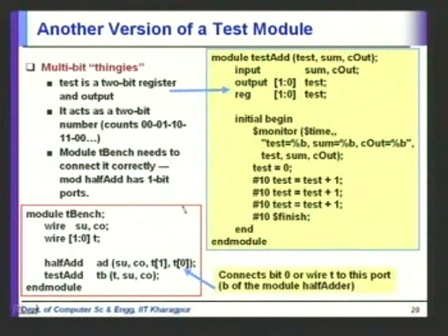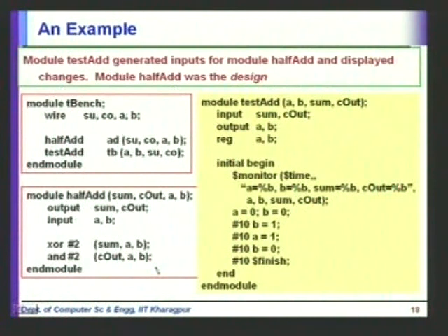Can't we just pass it as just T and access them separately in the... If you could have declared in your half adder, you could have declared T to be a 2-bit input, but then this code will have to change. So then this code will have to be rewritten, so that this is not declared as 2 inputs A and B, but as 1 input A with 0:1. Right? Then again, these would have been A0, A1, and things like that.